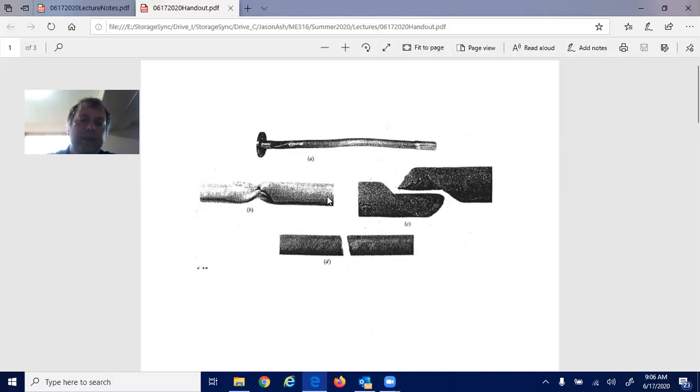And so you might think, well, let's just make this a really big diameter shaft with a small wall thickness. This is what can happen then at that point, is you end up with elastic instabilities and torsional buckling. So one thing you have to be cautious to realize is that there is that potential for elastic instability with cylindrical tubes.